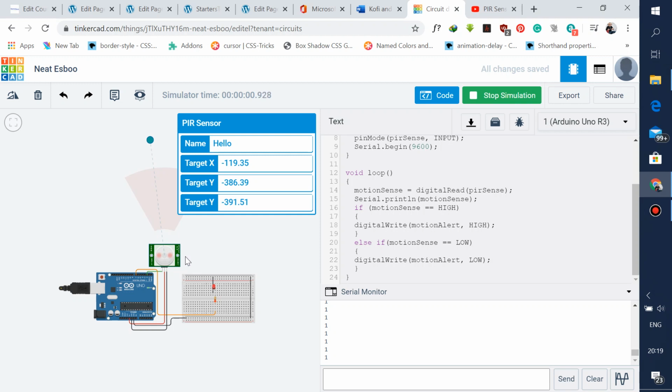One thing I forgot: the PIR sensor has a potentiometer. The potentiometer allows you to calibrate its sensitivity. So I think that it takes time to detect when the object is no longer in its space. Well, now it's a 0 and it's gone off. So with the else if I didn't really change anything, I'm still getting the same values. So do the PIR motion sensor connection and know that it takes time to read. That makes sense, because after the body leaves, depending on the sensitivity of the PIR, the infrared signal might not disappear instantly, but with just a little time it will come back to normal. So this is a pretty simple one.